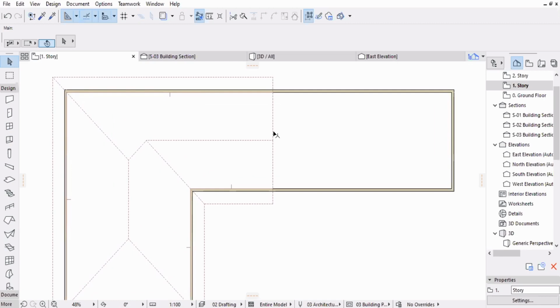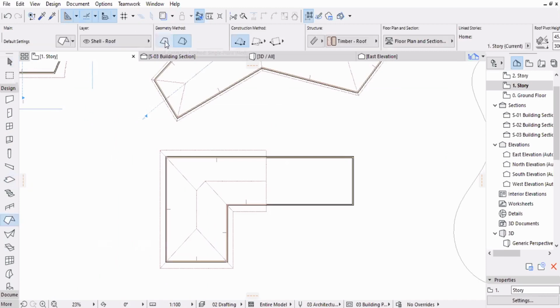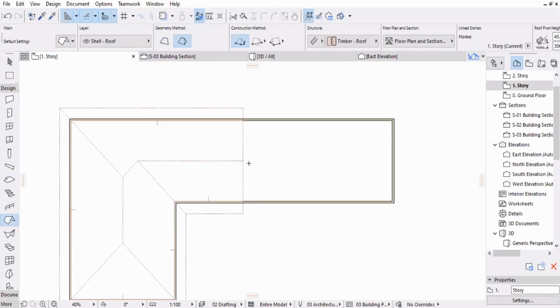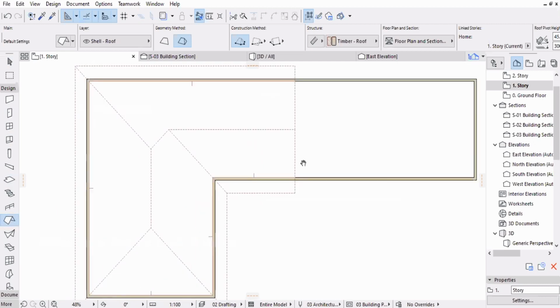Now I can either keep this as a gable end or I can put a hipped end. But for you to put a hipped end here, you will have to draw a single plane roof using this command here, from here to here, sloping on this side. And then you'll have to do some editing options within this three-roof-pane, single pane. You'll have to do some editing options which I have not taught you as yet, so we will not do it now, we'll do it later.